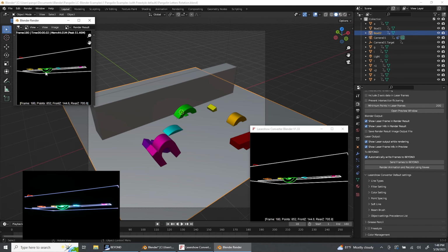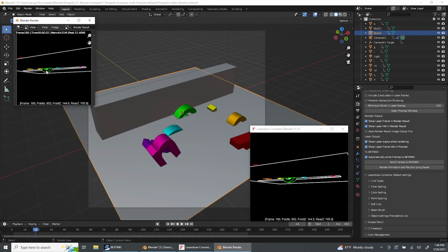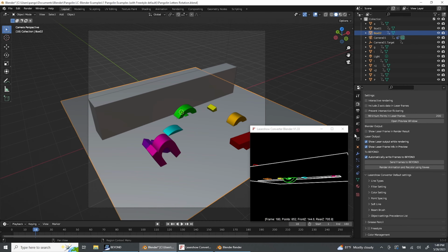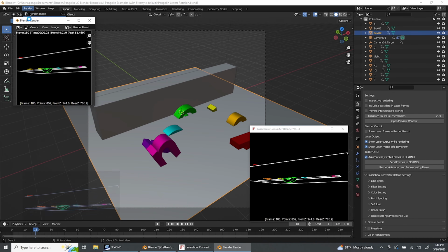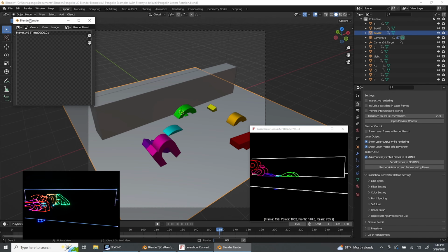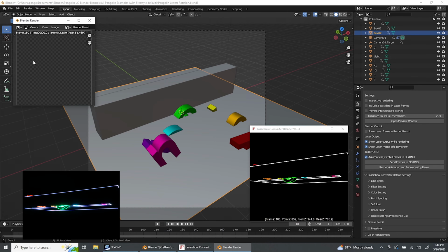And in fact, if we want it even faster, what we'll do is turn off output to this window here, the Blender Render Preview window. It turns out that writing to this window is very time consuming because each pixel is 4 32-bit values that we have to write. And so the bigger this window is, the slower the rendering into this window is. But with this option here, we can stop output directly to that window completely. And when we run this again, you see the rendering is even faster, and there's basically no output into this window at all. The window still pops up, but there's no output. So that gives you the fastest rendering.